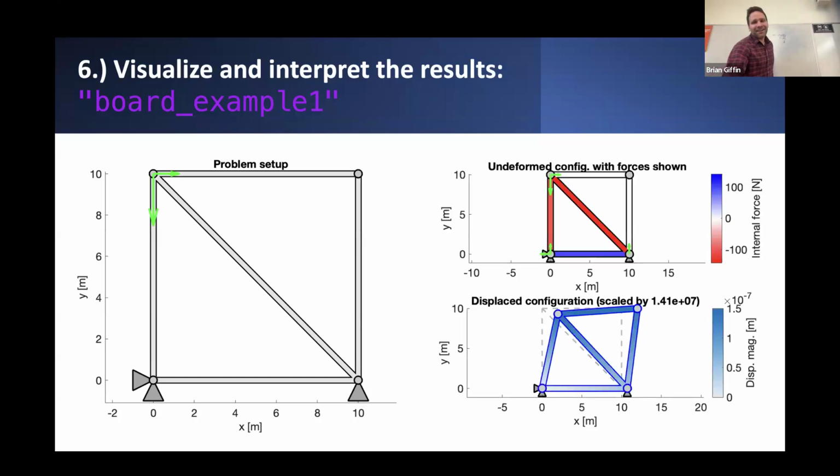As for the other members, certainly these two vertical members are going to be in a state of compression. That makes good sense. If we have a force here, it's pushing down. This member is also being pushed to the right because we have an extra force here and a force pushing down. The bottom one is in tension, though. So what's the rationalization there? Why is that one in tension? Because the diagonal member is in compression. Yeah, so it's to balance the.